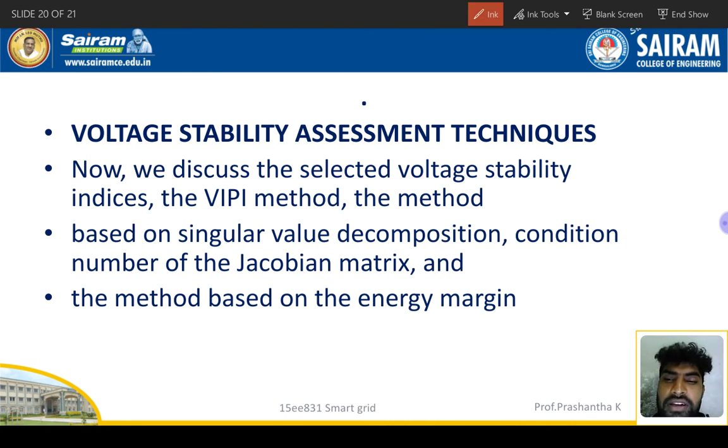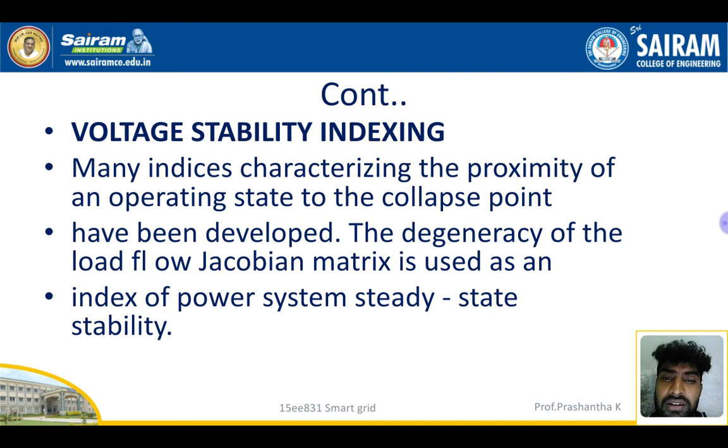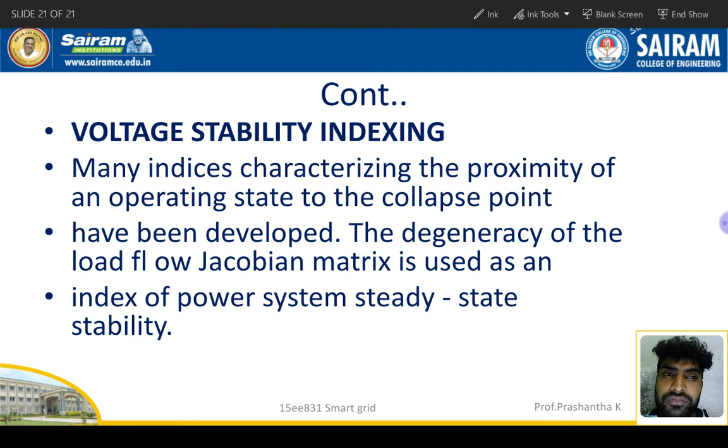Voltage stability assessment techniques. Now we discussed the selected voltage stability indices. The methods are based on the singular value decomposition and condition number of the Jacobian matrix. See, the Jacobian matrix is used to determine stability analysis, right? The methods based on energy margins will also be helpful, right?